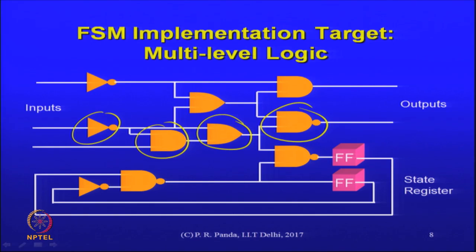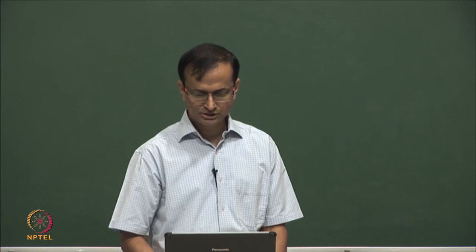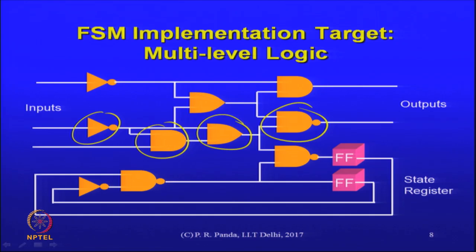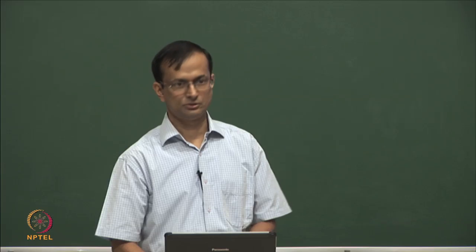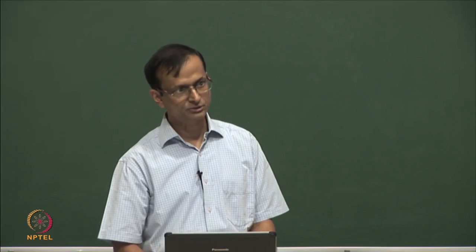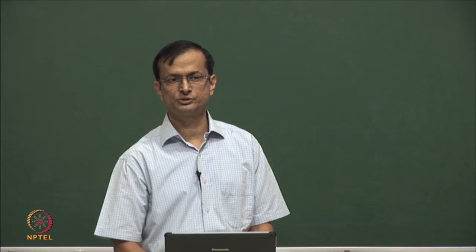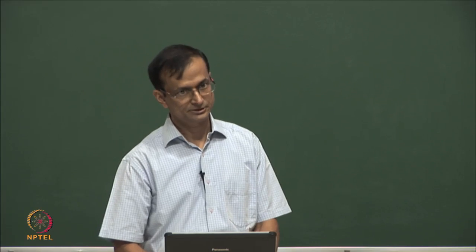Standard logic optimization techniques would indeed be applied after we perform the encoding. So, at this stage somehow we need to anticipate what happens there. Remember, we are not generating the circuit as part of encoding. We are only taking those decisions of the translation of the symbolic states to our distinct encodings. That is all that we are doing, but in the process of doing so we should anticipate what happens later.